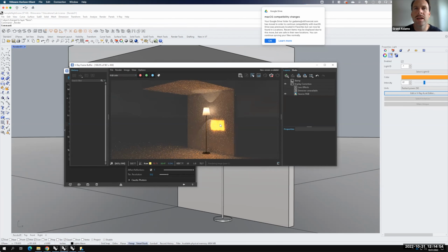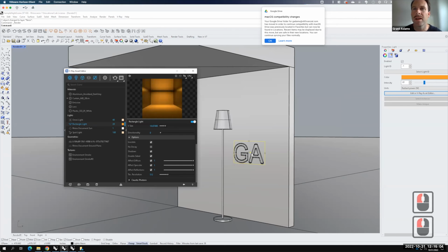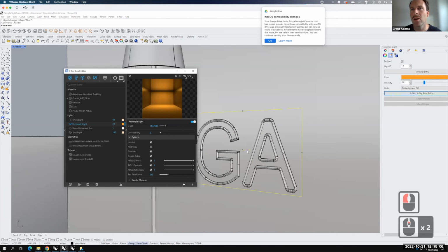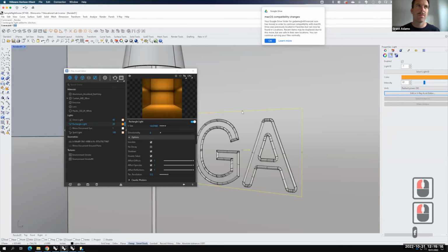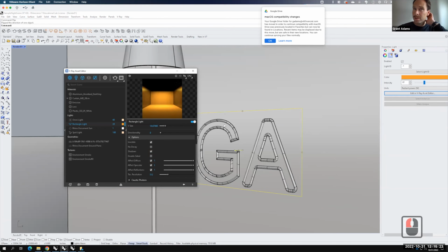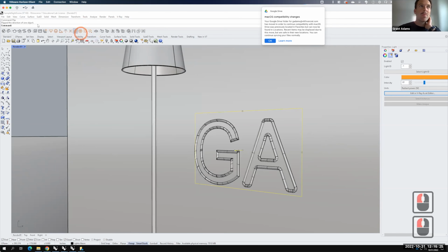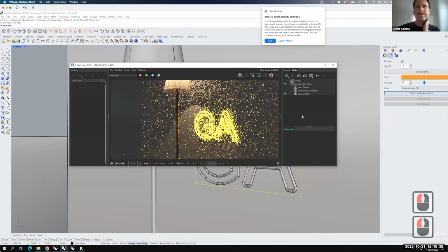And unfortunately, it is shining on the wall so bright because it's so close to the wall. So let's make a few modifications to it. And this is where you can see that there's always modifications to be made. So what I'm going to do is I'm going to flip this light away from the wall. So I'm going to type flip, and you'll see that arrow will flip, be pointing away. So let's type flip. And now the arrow is pointing out toward us. And then I'm going to uncheck double-sided. So it's just pushing light out this time, and we'll try another render.